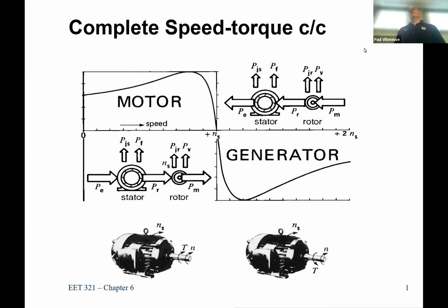Not really, because what do you need? You still need some sort of output voltage, if you will, that's going to give you that 60 hertz. So in an AC induction machine, you can spin it all you want, but until you have a voltage connected to it, some sort of a power source, you're just rotating something in a set of windings that's not doing anything.